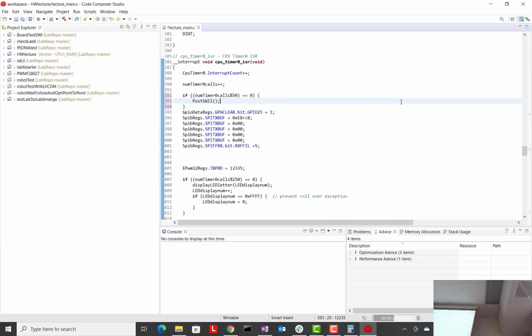With a lot of work. And so we're not going to go there. But the biggest problem with CPU 2 is actually debugging your code more than anything else. Unfortunately, if you were going to work with both CPUs, we just don't have time in this class to do it. When you debug every time in Code Composer, you have to download your code to CPU 1, and then you have to download your code to CPU 2. Then you have to start CPU 2's code, then you have to start CPU 1's code, and then you can debug. So it's a big process.